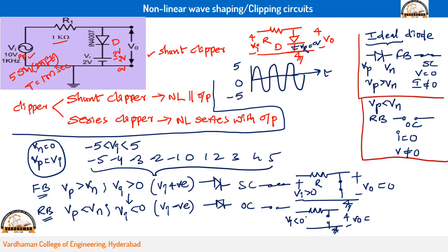See carefully here. Since it is an open circuit, in an open circuit an infinite amount of resistance is there. Sorry, that is in series with resistor R. So something added to infinity means again you will get infinity. That means there is no current through this particular loop. So current is equal to 0.